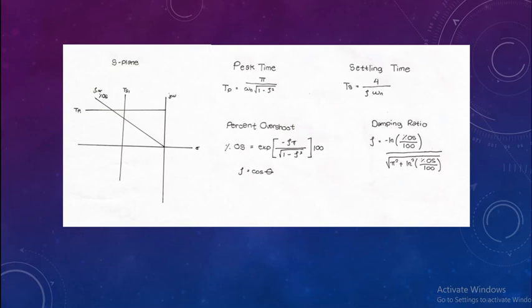So we are now tackling how to solve our root locus through the transient response design. But we are going to use a different approach of solving through simply adjusting our gain. Now, let's say we have a given root locus and we are to adjust the gain by moving our closed loop poles to a different point on the root locus. And if we move it to a certain point, we will be able to get the desired characteristics, which are the settling time, the peak time, the percent overshoot, and the damping ratio.